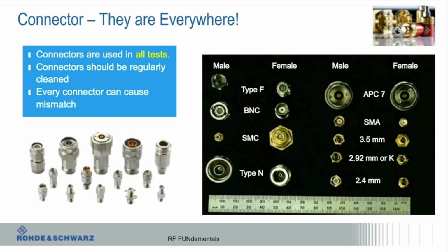3.5 is a precision connector, so it has an air dielectric. It doesn't have the white stuff there. It's an air dielectric with very precisely machined tolerances. Guess what? They cost more. Your manager probably doesn't like that. They'd say, buy the SMA, I like the cheaper ones, but it's got to work. If you look at the specs, there's a spec for a 3.5 millimeter connector in terms of frequency range, VSWR, and all that. I think it goes up to 26.5, just off the top of my head. With SMA, you'll see stuff where they'll say 18 gig. It depends. It's not a standard.